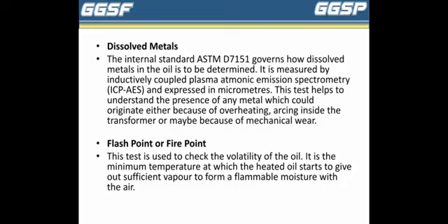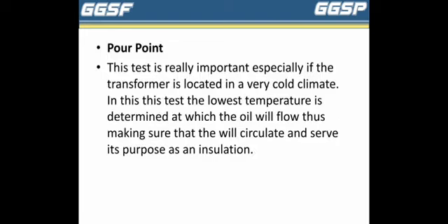Flash point or fire point. This test is used to check the volatility of the oil. It is the minimum temperature at which the heated oil starts to give out sufficient vapor to form a flammable mixture with the air.